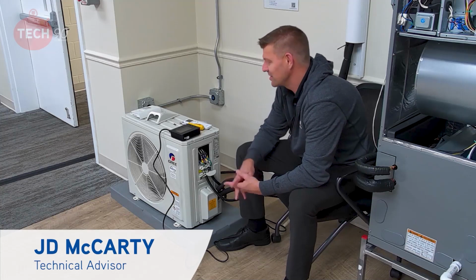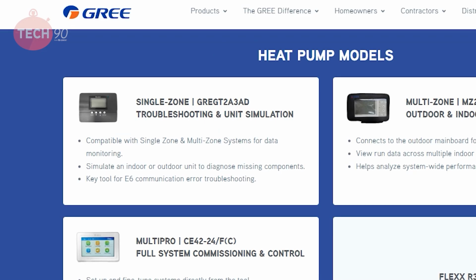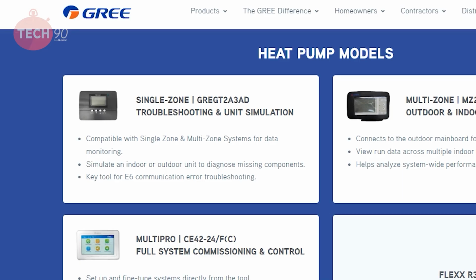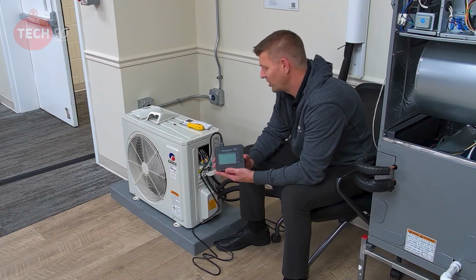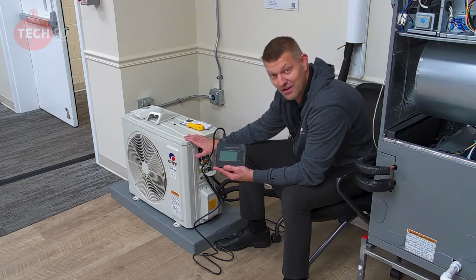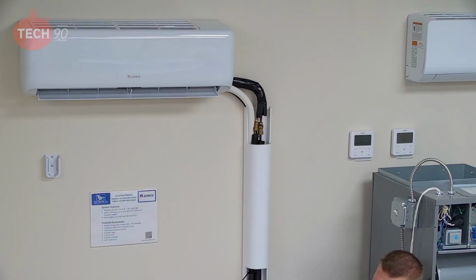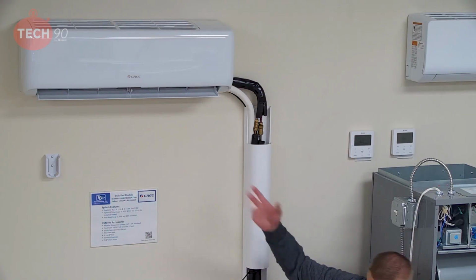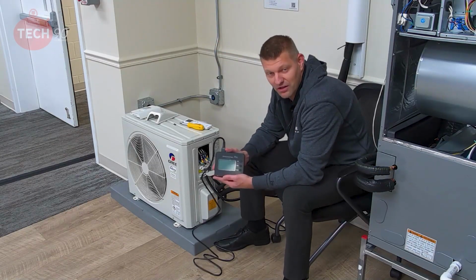Hi, JD with GREE. Today we're going to be troubleshooting an E6 code. We're going to be using the GREE single zone testing tool. The part number is GREG T2A3AD. So we have an E6. What we're going to do is use this tool and hook up to the outdoor unit and simulate the indoor and bring on the outdoor to see if the issue is in the outdoor. If it's not, then we're going to hook it up to the indoor unit and simulate the outdoor and bring on the indoor to see where the issue is.